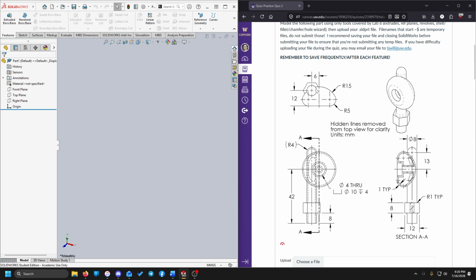From there, we can then do a solid offset extrude for this hexagonal collar, and then it looks like we do have some fillets applied on the outside of that. You can see it with the dashed lines in our isometric, that we do have some curved surface meshing in with another surface.